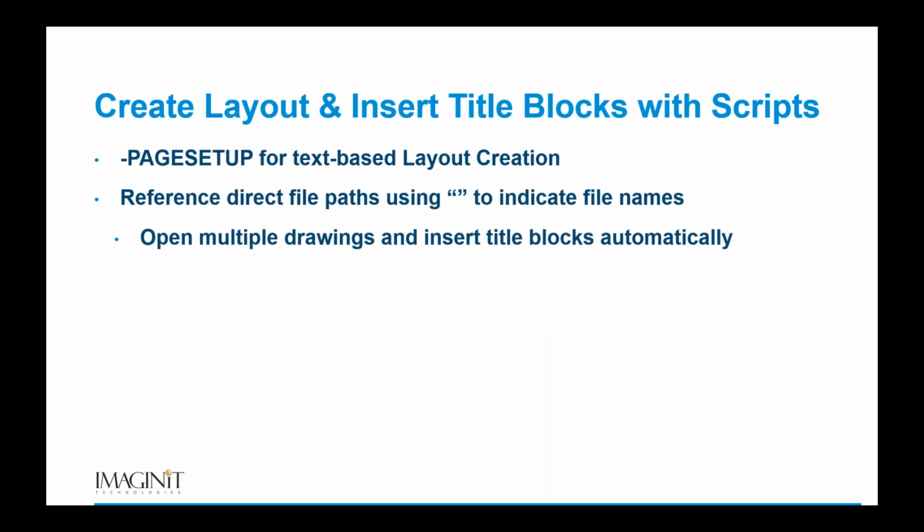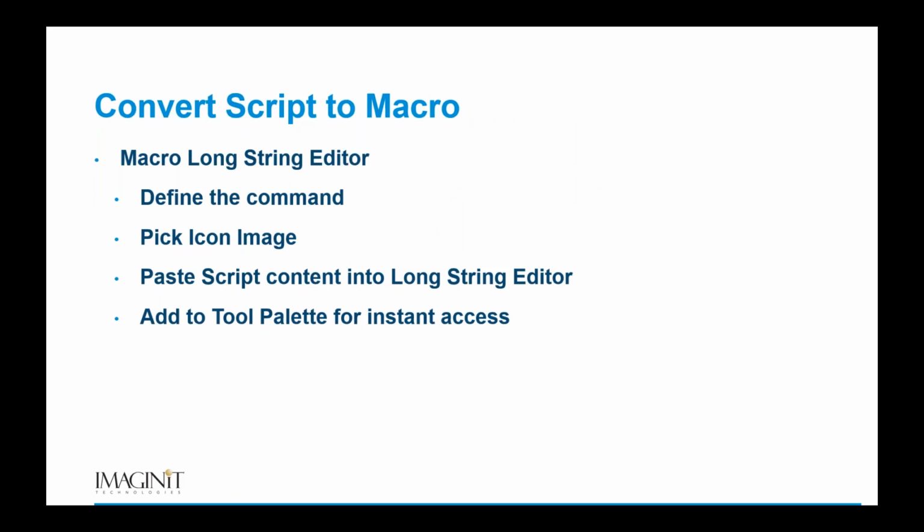The page setup command is something that you can run with that quotation mark for the file names. The quotation marks have been kind of tricky with scripts that I've been working on. For example, the PC3 file, that DWG to PDF, it doesn't like quotation marks around that one. So I had to go back and put in the underscores for the file name there. But it did allow me to use the quotation marks and keep the spaces in for the actual title block drawing file that came in. So in some cases, it is some trial and error and some editing along the way.